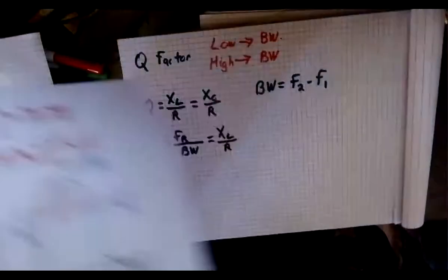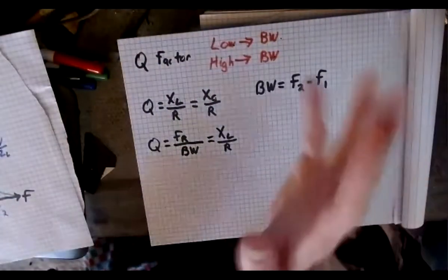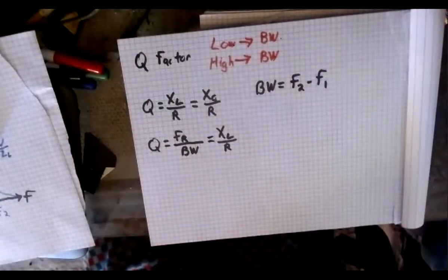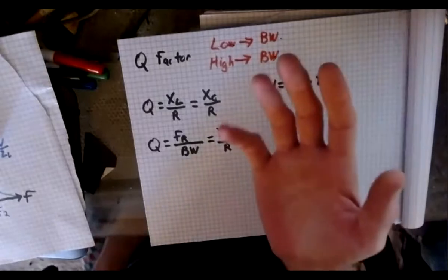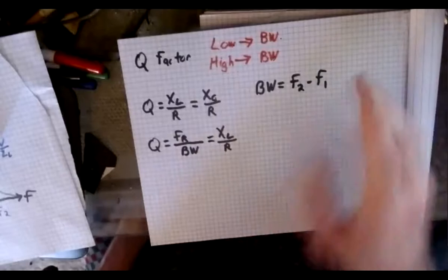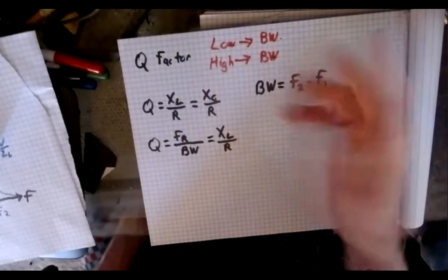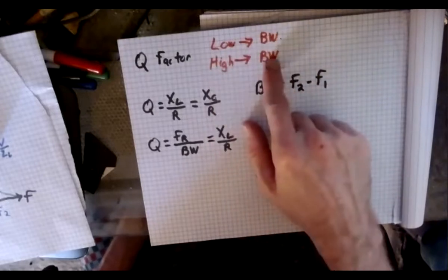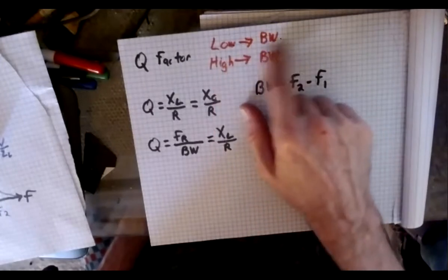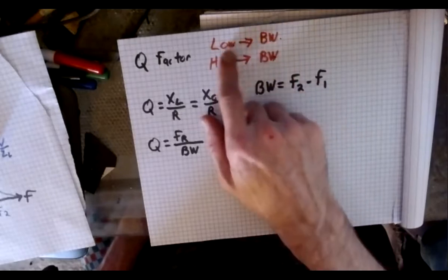And then based on that, then we look at our final Q factor. And just remember now, this is really a ratio. It's a model that we could use, and it's partly from a design standpoint. I'm not going to lie, right? I mean, why would I be interested in that? But from a design standpoint, if I were interested in a real tight bandwidth, go high Q. A real broad bandwidth, or I don't really care so much, you go low Q.